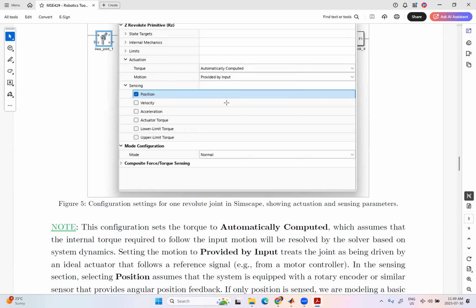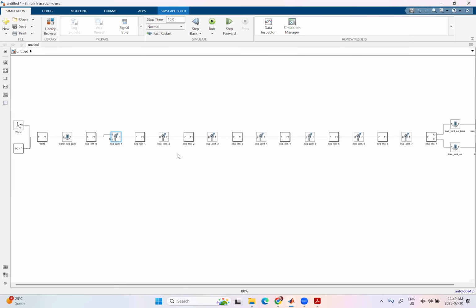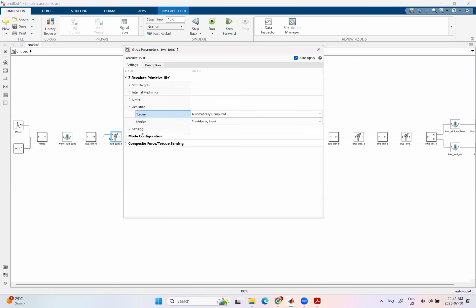And what sort of sensing mechanism, what sort of encoder do you have? Is it just an encoder that measures angular displacements, or do you have a gyroscope, for example, in an acceleration measurement application? In this case, we just need to check mark position for the Simulink model. These two are set, and then the sensing configuration mode is position.